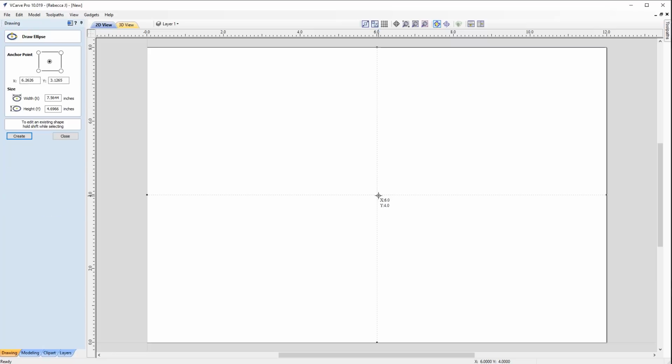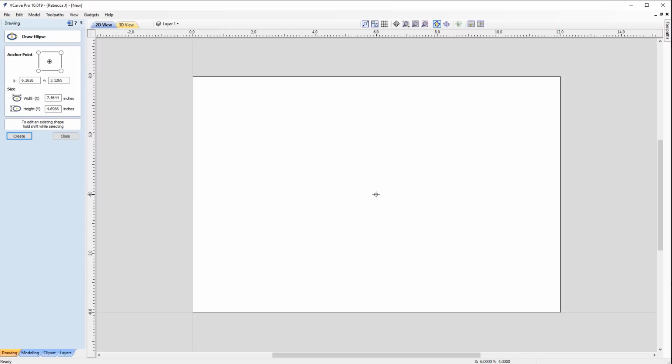Okay, so I'm going to snap to the center point. Because I've got my snap settings switched on, I'm able to locate the dead center of my job space. You can see the dotted line here, so I'm now snapping to the center there, in which case I can go ahead and stretch out an oval, give that a little bit of height, just make that a little bit bigger. Okay, something like this looks okay, so we'll go with that as our basic shape.